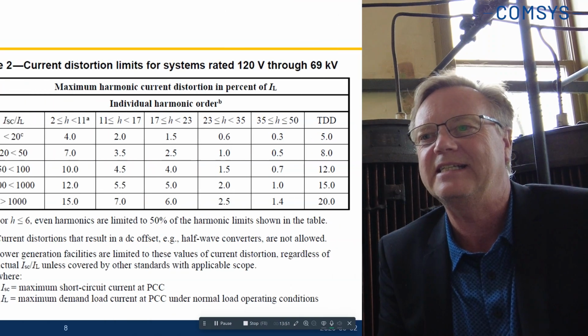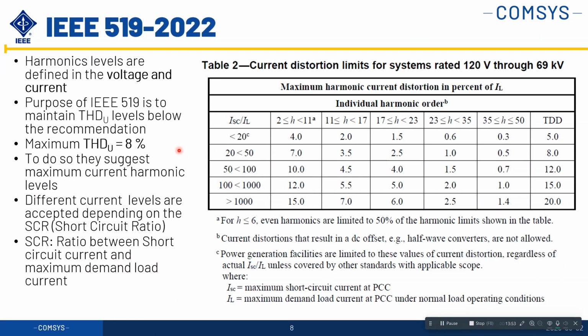But I would say this is where I'm getting a bit questionable on the IEEE 519, because it's really the voltage distortion that will harm your equipment. Yeah, current distortion is not good, you can heat cables and so forth and breakers. But the limitation you see in this chart really makes us oversize also the active filters for the systems. We're going to reach 2-3% with the limits you have in the chart to the right on the current distortions.